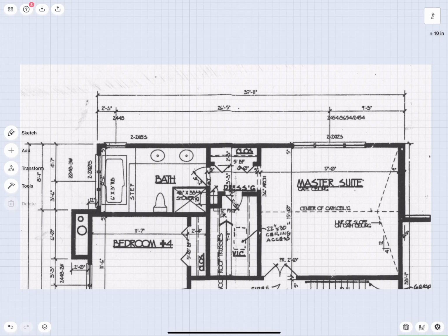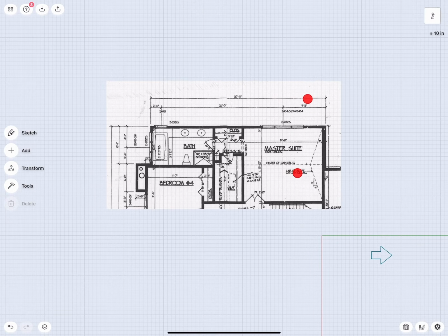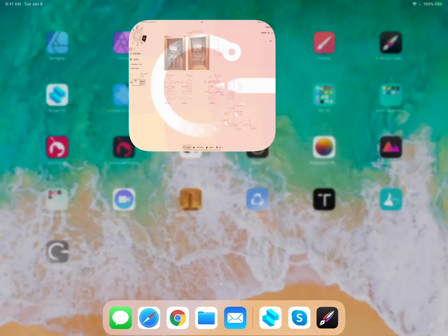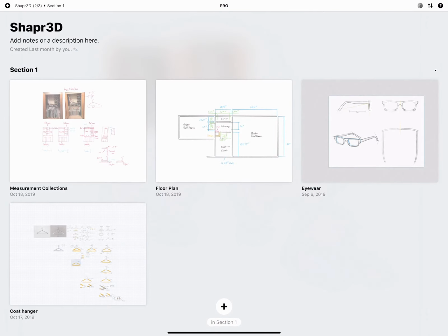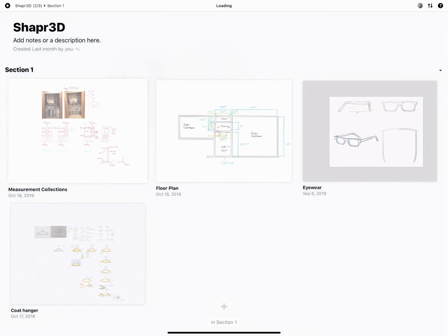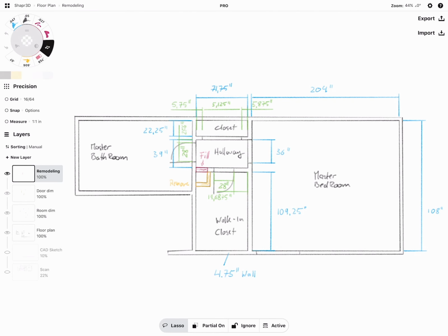So what I did, I used those drawings, and then also went to the property and took some direct measurements inside of the space, because the construction document is one thing, but during construction, changes might happen. Something I tell my students very often is don't trust a construction document you didn't manipulate or create yourself, because you don't know if changes that happened during the construction of the property are being reflected back into the original construction documents.